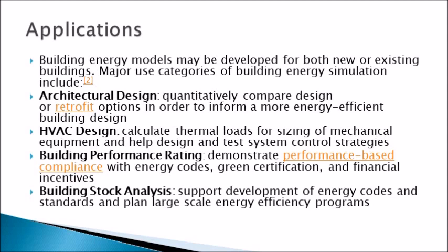And for new buildings, similarly, you can propose various options of whether your building wants to be tall and slim, or compact, or going to be elongated east and west regarding the orientation, so on and so forth. So all these choices will have different energy outcomes. So the beauty of this is that you can have various configurations, various scenarios of your building architectural design, and you would be able to quantify the performance in terms of all the parameters mentioned earlier.